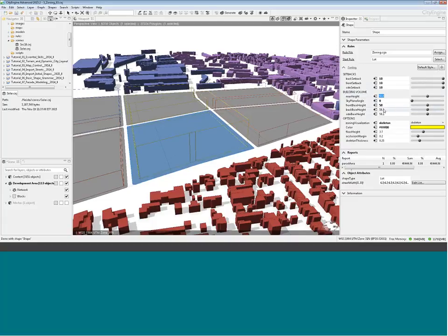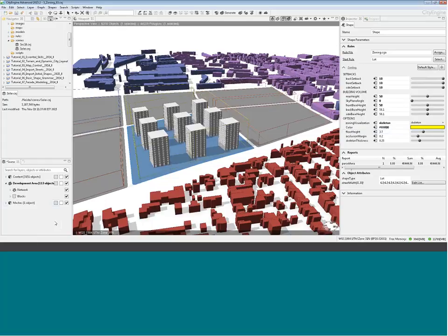Similarly, we can set multiple properties, and there are visualization patterns available. For example, currently we have selected the skeleton. This way we can select the transparent, which will give you a more realistic view of what could be the maximum height of the building. We can select no horizontal surface, which means there will be no roof, only the side walls. So this way we can select multiple scenarios. Now we'll go one step ahead and try to create a building inside the zone.